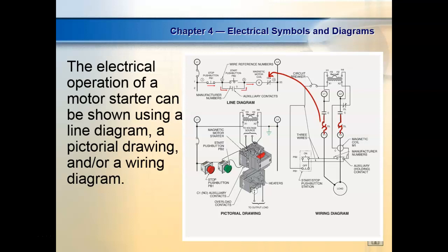These things. This is originally, this is a motor. So what you'll find out on a motor starter is that they got a nameplate on them, and usually they give you the horsepower that this thing can run. Now, I don't know if we can pass this around or not, but what you'll notice, the higher the voltage, the bigger horsepower the motor can run. And why is that? So it's normally about 746 watts per horsepower.